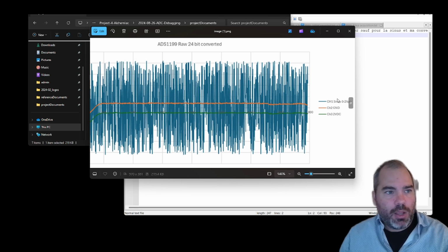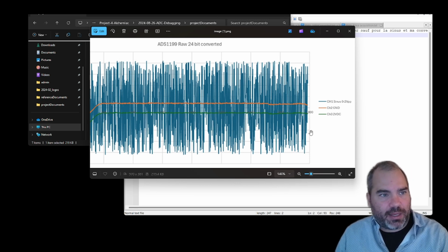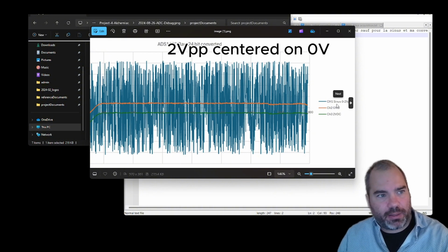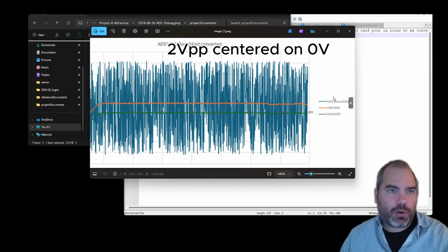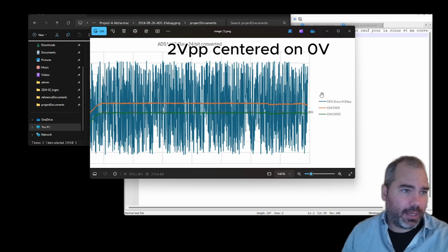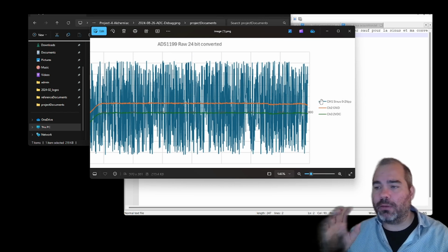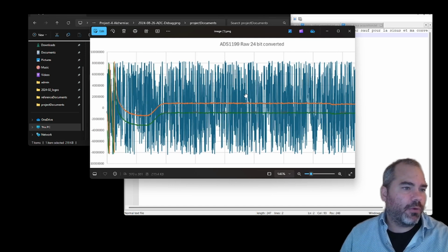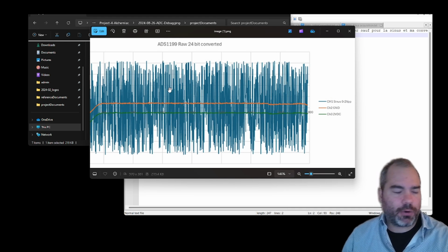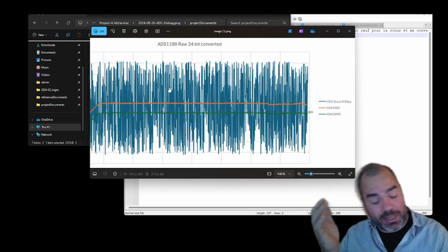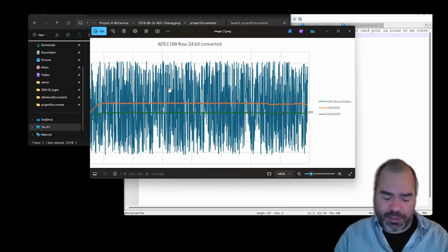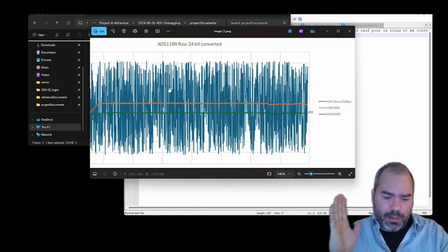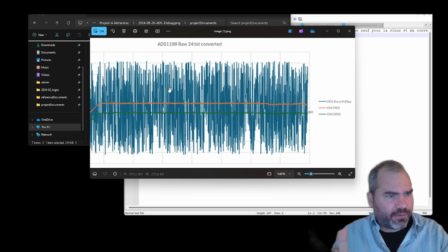And then we have here a 0.2 volts peak-to-peak sine wave, and the frequency is 50 hertz. This is well within the admissible bandwidth of what we're trying to do. We're sampling at 250 hertz, which means that we should be able to sample correctly anything between 0 and 125 hertz, give or take.